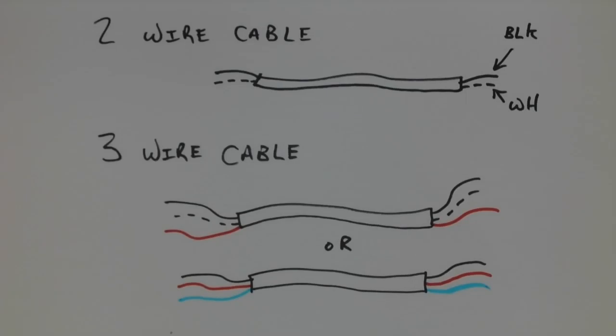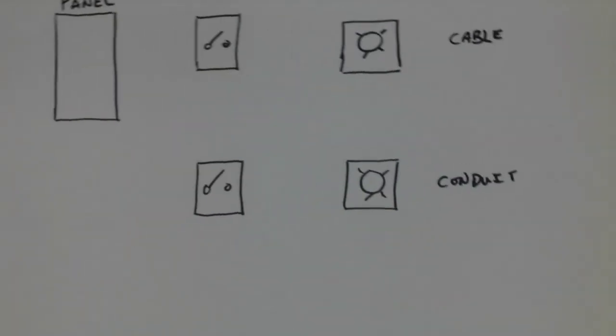Now, the challenge in wiring these standard lighting circuits is that the white conductor does not get to be used in any way we choose. There are some specific parameters around that, which are covered under Section 4, Uses of the Identified Conductor.